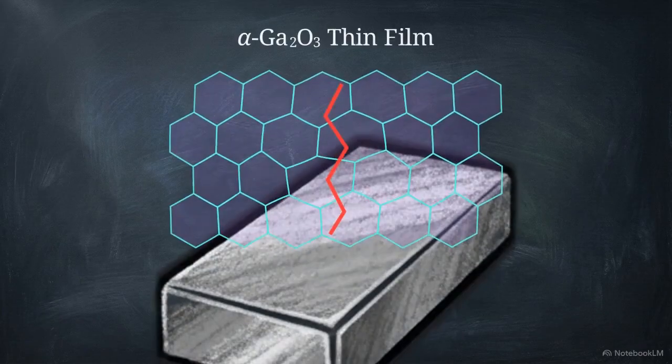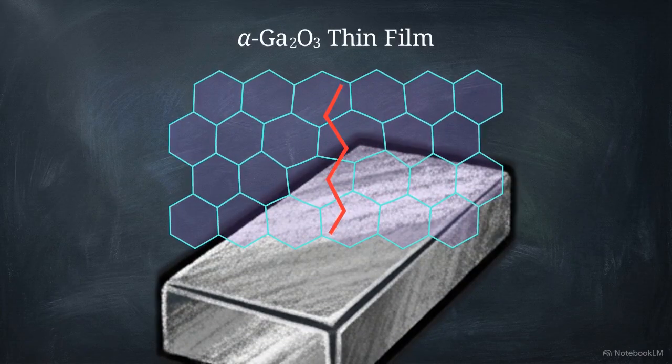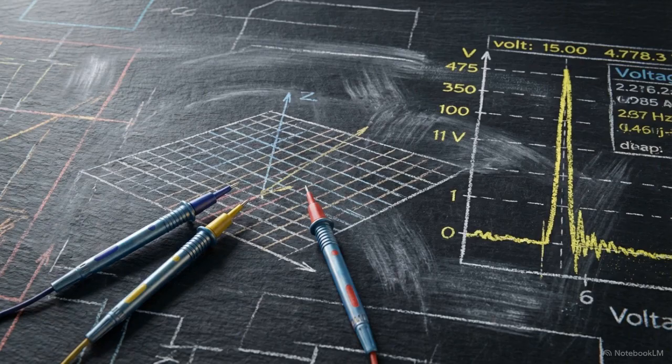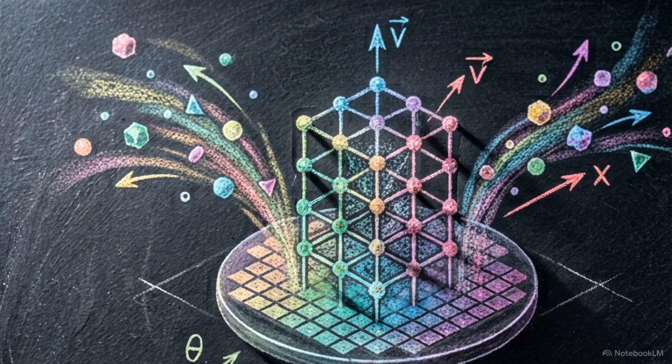It yields remarkably low dislocation densities, meaning the crystalline structure contains far fewer physical defects. This mist delivery mechanism ensures the successful growth of highly transparent, conductive antimony-doped tin oxide films, as well as high-quality alpha gallium oxide layers on specialized templates.